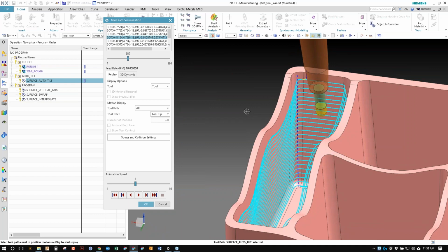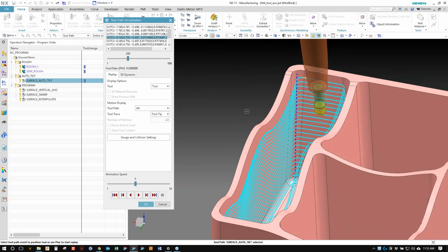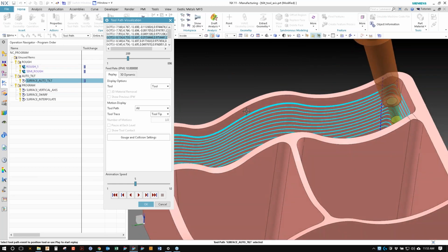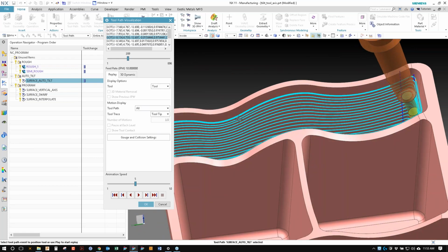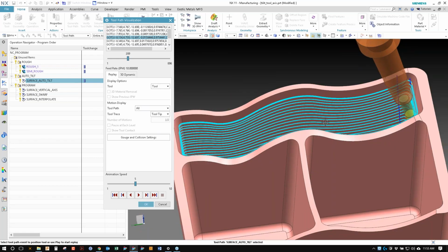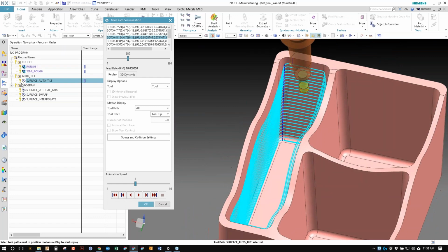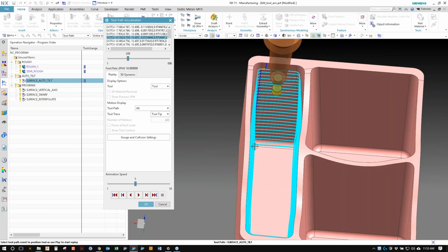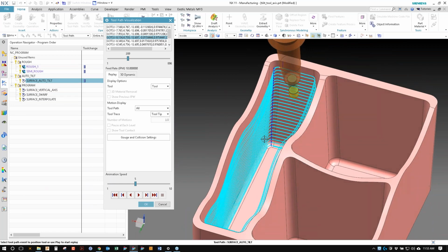So I like that it will cut portions that don't have collisions in just a normal 3-axis mode, which will usually cut faster, and why tilt if you don't have to? If you tilt the Swarf that already has tilt on the entire toolpath, you'll have that tilt from the top to the bottom, and then it will just adjust the tilt in the corner.